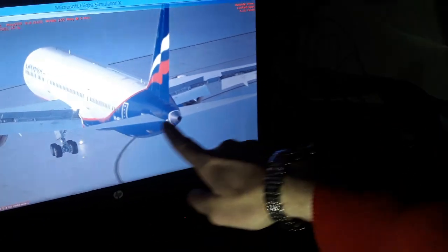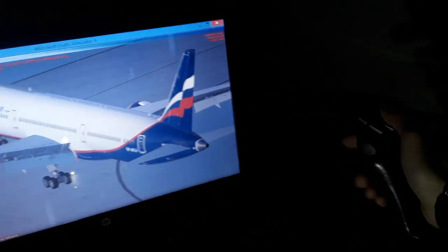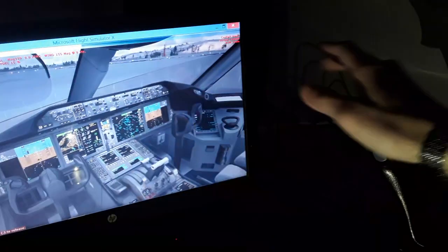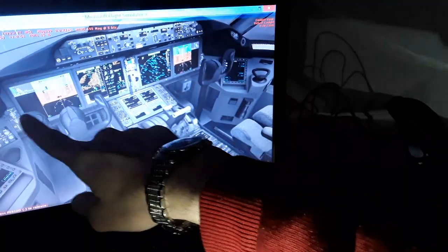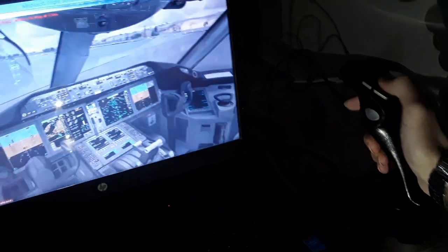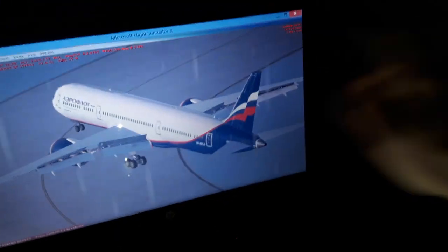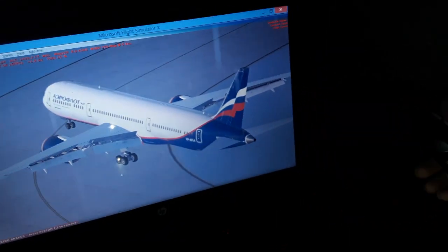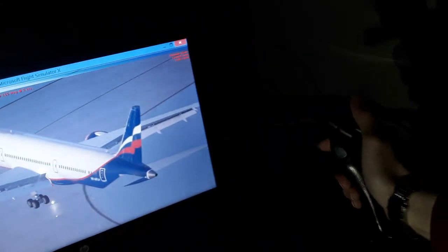We have also the horizontal trim stabilizer. We can trim the elevator trim. So we have this elevator trim switch here, and the alternate, the normal and the alternate, and the cutoff switch for the auto trim system. I have the trim system over here on my side stick. So I will keep talking to you about this. There is also another axis, the longitudinal axis from nose to tail. It transverses the others, the vertical and the lateral axis.